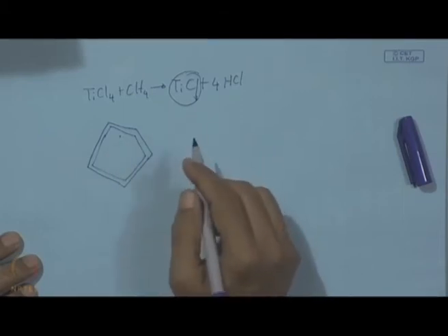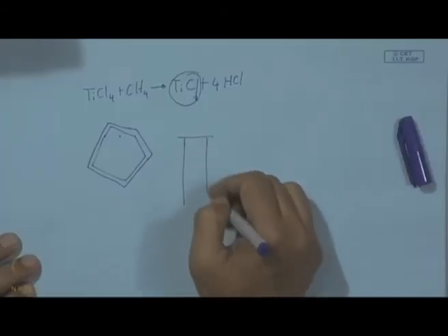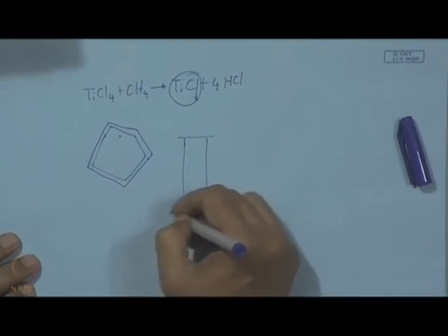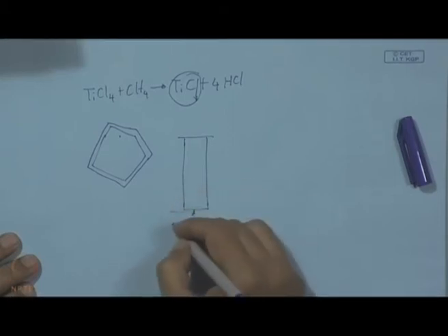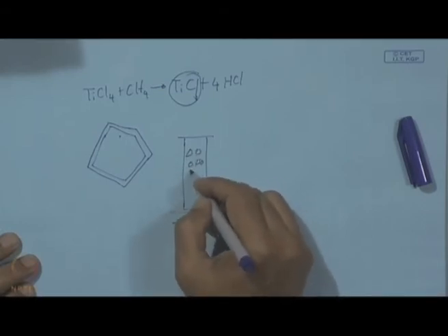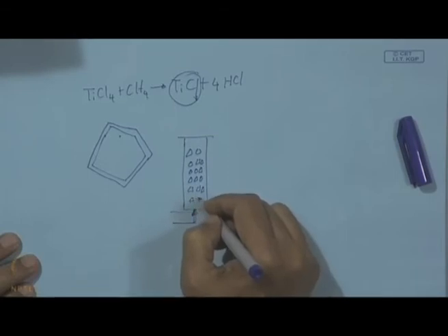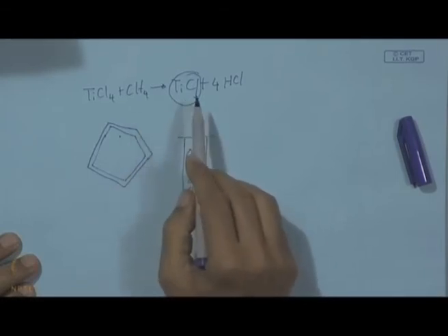Of course, in this case what is necessary is not a conventional reactor, but a fluidized bed reactor, so that in the vertical tube reactor there will be a suspension of the grit material. So, all the reacting gases should be fed. It is almost like a vertical reactor, and the reacting gases will be fed from the bottom. Here the grits will be like suspended particles, and on this grit surface the reaction will take place.